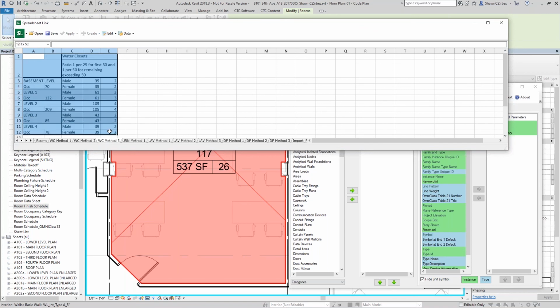Now this is something that I might want to bring back into Revit with the background cell infills, with the heavy lines, the medium and light lines, all the stuff. I want this in my Revit model so I can put this on a code compliancy sheet or my cover sheet and do things with it. But Revit can't bring this in directly, but our toolset can. So hang on a second here.